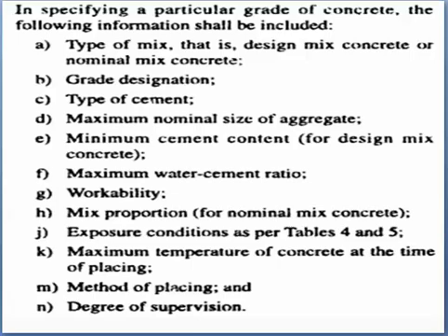Then grade designation. If we are designing the mix, then we should be clear about the grade of that particular concrete which we are going to design. Then type of cement: either it is PPC or OPC, which grade of cement we are using, which company of cement we are using. So we should know this information before going for the mix design.